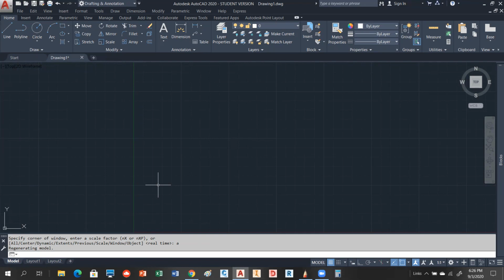So now we're going to take a look at the polyline arc options. Arcs for polylines are just as complex as they were for this type of arc. You're going to see when we get into this, there's a lot of options. But the one thing that's really cool about the polyline arc is it automatically pretty much goes tangent from the last object. So that's a really nice feature.